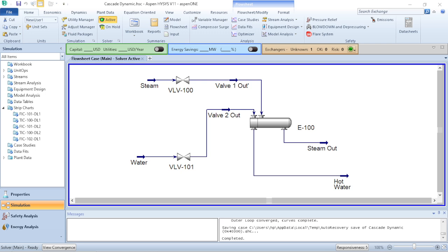Let's get into it. A Cascade controller is a control system configuration where two or more controllers are used in a hierarchical arrangement, with the output of the primary controller, also known as the master controller, serving as the set point for the secondary controller, also known as the slave controller. This setup allows the system to respond more quickly and accurately to disturbance by controlling an intermediate variable that directly influences the main process variable, improving stability, accuracy, and dynamic performance.